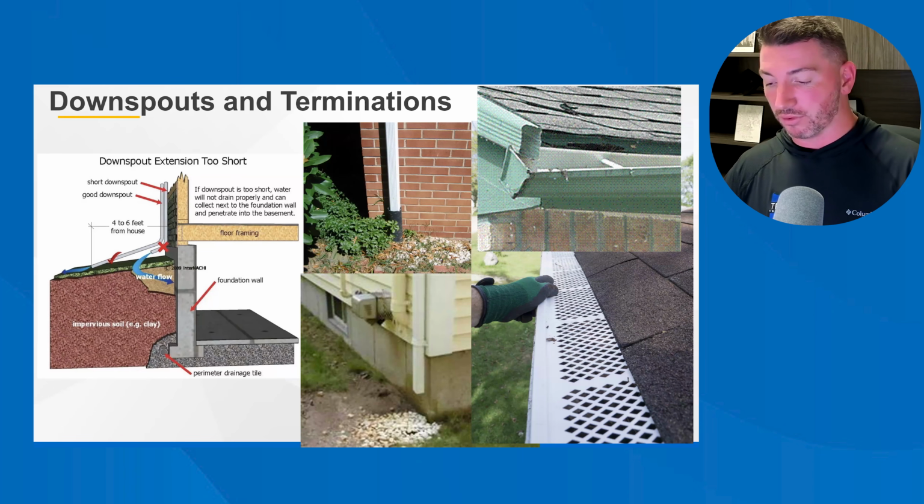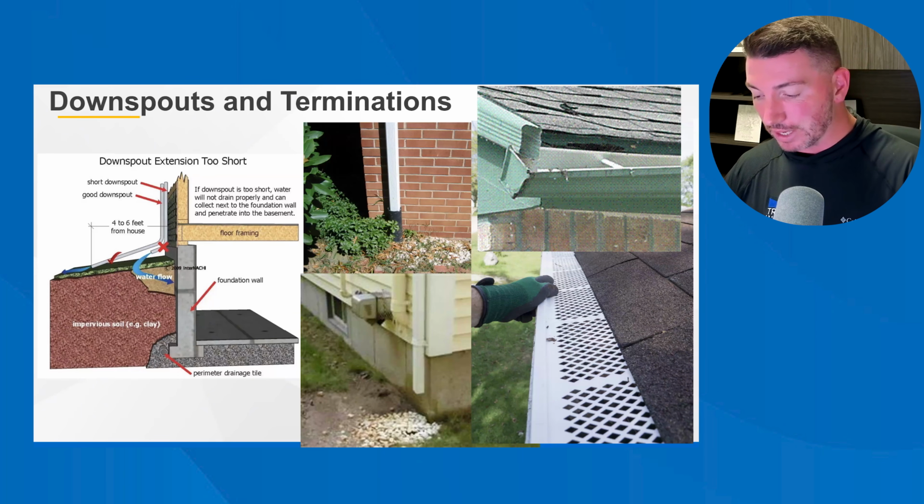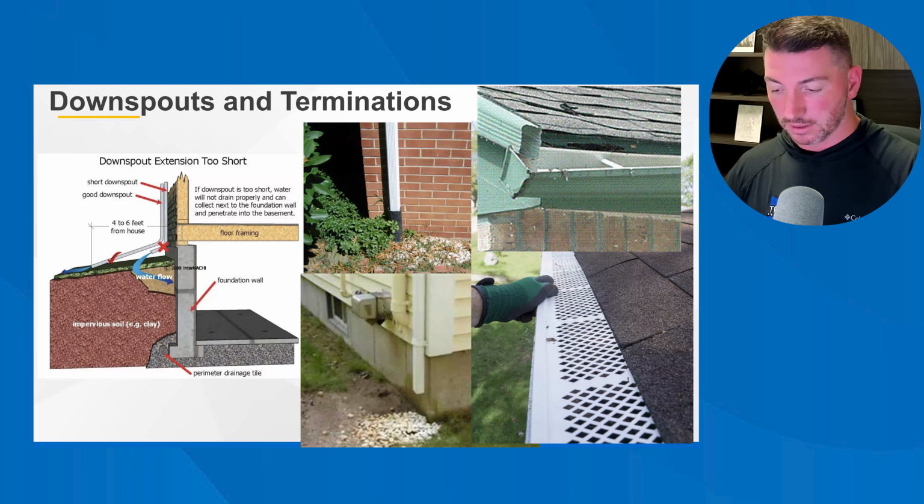So if a common 2x3 downspout can manage 600 square feet using our general rule of estimation, then we need at least 3 downspouts to serve that roof, right? If that makes sense: 2x3, 6 square inches times 100, is 600 square feet that downspout can handle. So you estimate the size of the roof, and if you're using 2x3 downspouts, you can manage 600 square feet of drainage for each downspout. And if it's a 3x4, you can manage 1,200 square feet.